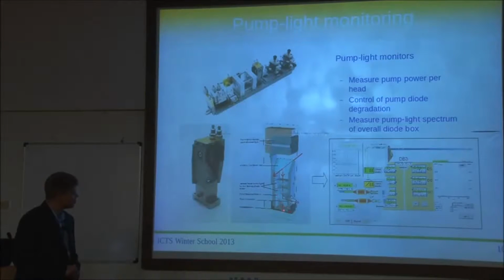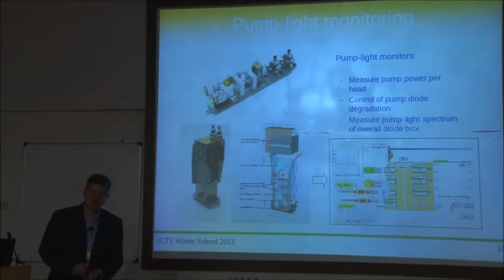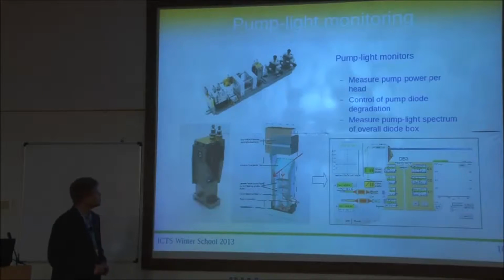There's another beam splitter here, and then we have a photodiode here which monitors the power, or it basically just gives you a voltage, and another fraction which comes out here, and then there is a fiber connector here, it's maybe easier to see here, and the fiber can be connected, and then the light can be analyzed in terms of the spectral distribution of the components.